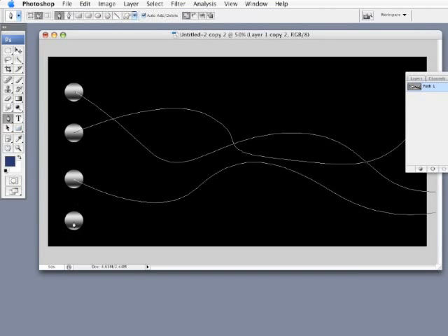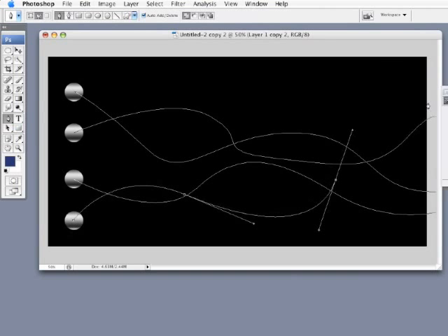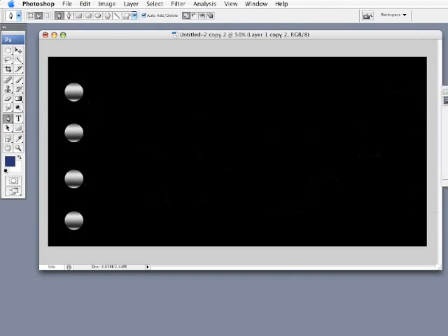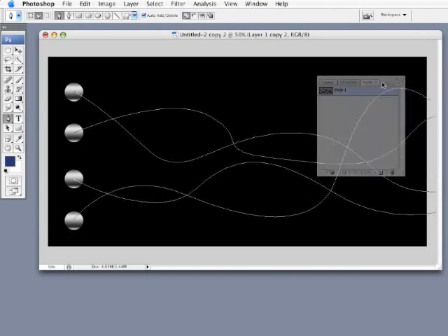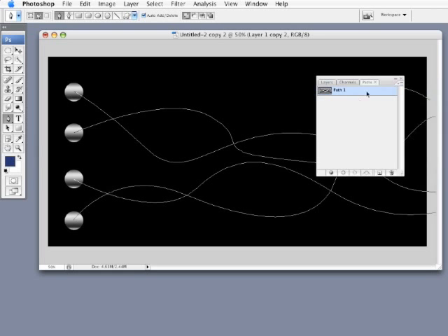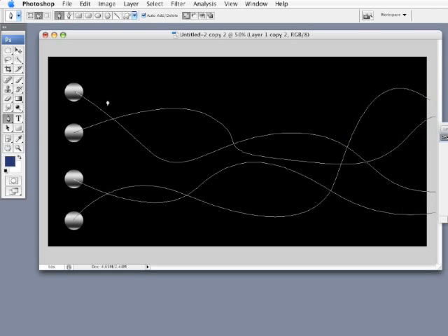And let's get my path tool, and I'm just going to click a point right in the center there. And we'll just kind of draw a shape out here. And just go right off the edge of the document there. So now I've got all my paths in place. These paths are going to be used to generate the next effect we're about to do, which is, I'm going to go over here to the Smudge tool, which is located where the Blur and Sharpen tool are. We have the Smudge tool right here.